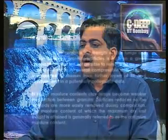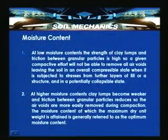As we have seen with moisture content, we also saw the importance of the role played by water in compaction. So, let us look at how the soil behaves on the dry of optimum and wet of optimum in this section. At low moisture contents, the strength of the clay lumps and friction between granular particles is high. So, a given compactive effort will not be able to remove all air voids, leaving the soil in an overall compressible state.